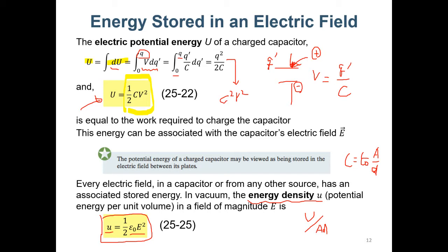Because if you have a clock, you have the charging and the discharging. So you have 1/2 CV squared, and then the other 1/2 CV squared, and then totally it will become CV squared. And then in a second there will be f times. This is the frequency f hertz. So you multiply the energy by f, so that it becomes the power. Maybe you will see it in a later course. I don't know.